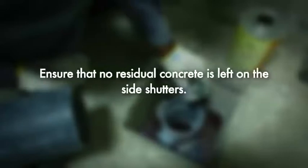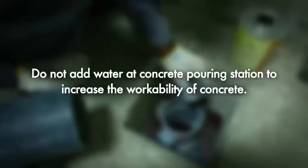Don'ts during precast production. Ensure that binding wires and rebars don't touch the shuttering. Ensure that no residual concrete is left on the side shutters. Do not add water at concrete pouring stations to increase the workability of concrete. Do not add excess water or cement on concrete surface to facilitate the surface finishing.